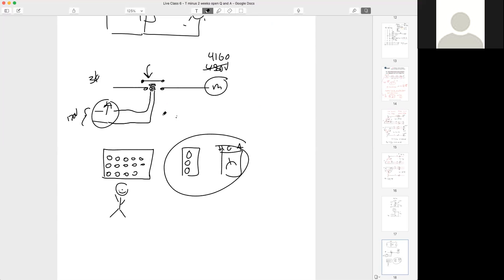You can also go one step further. PLC, you have a contact, right? You have your 120 volt coming in. That's going out. Maybe your PLC is now going to your relay. And your PLC acts essentially like a relay, except you have a program. When the program is satisfied, it closes this contact, which flows power from your hot through your PLC contact output to your relay, energizes that coil, brings your contacts down, and passes through your higher voltage to your load.